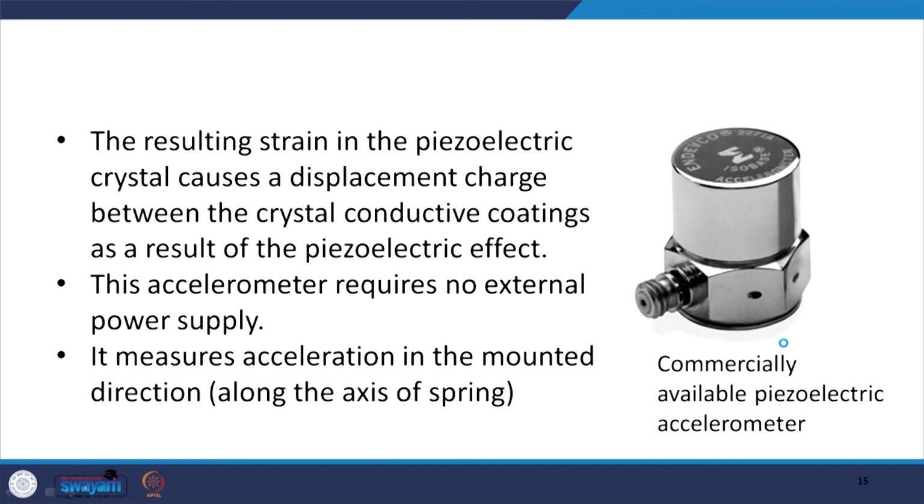Now, when the vibrating object experiences acceleration, we have seen that relative displacement occurs between the object and the mass due to the inertia of the mass. Now, this resulting strain in the piezoelectric crystal causes a displacement charge between the crystal conductive coatings, as a result of the piezoelectric effect.